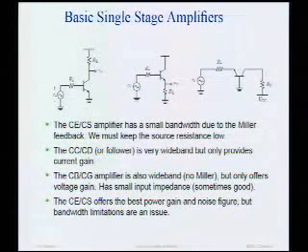Well, we all know that the weakness of a common source amplifier is bandwidth reduction due to Miller effect. Miller effect happens because we have a parasitic capacitor from the base to the collector. And it's a pretty small capacitor. It's something you might be able to live with. But if you're greedy and you try to get lots of voltage gain out of this device, we get Miller multiplication. In other words, we get a capacitance at the input which is Miller multiplied by the voltage gain. So if the voltage gain is 10, this small capacitor is all of a sudden 10 times bigger, and it appears at the input. And that means that it's going to basically produce a low-pass filter at the input of the amplifier.